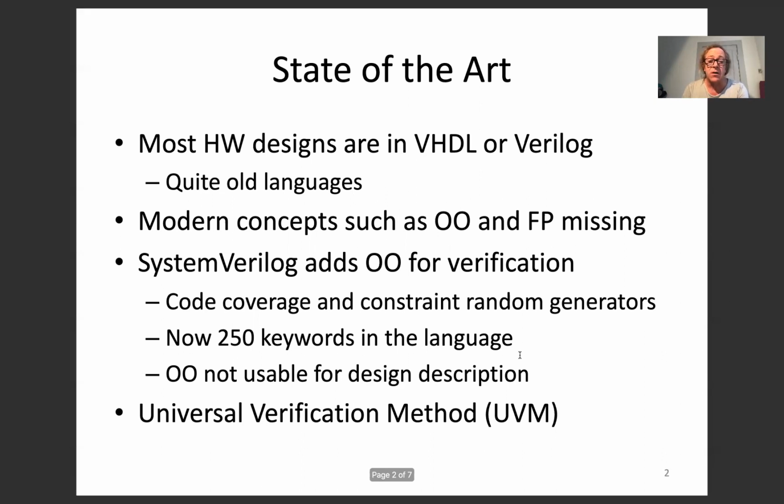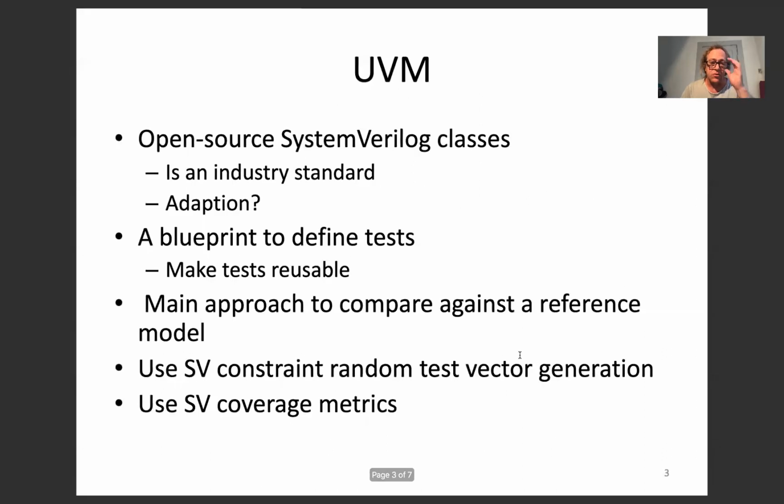On top of SystemVerilog, the Universal Verification Methodology, UVM, has evolved for verification. It is a collection of open source SystemVerilog classes and is considered an industry standard. As for adoption, I don't really know how much it is really used. I've done some questionnaires in Denmark. There are quite a few hardware companies here in the greater Copenhagen area, and all state they're looking into UVM, but not really using it yet.